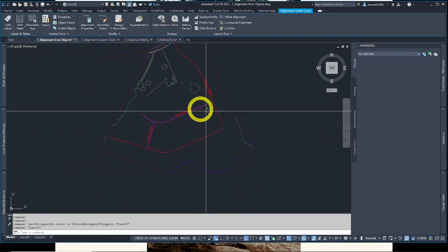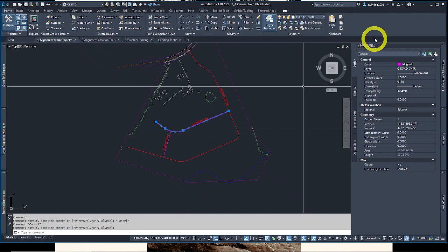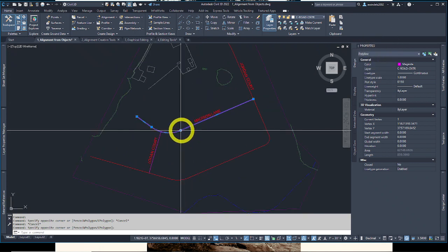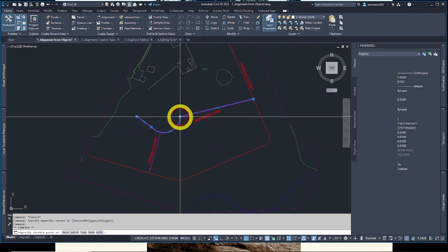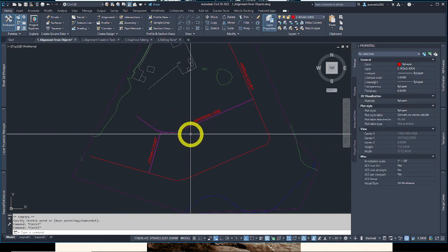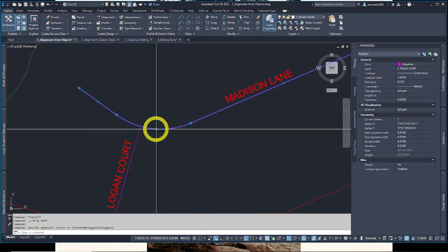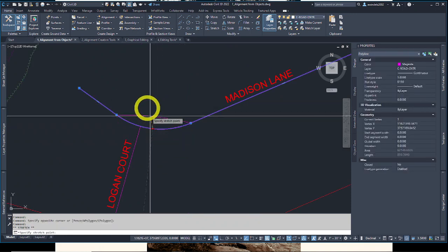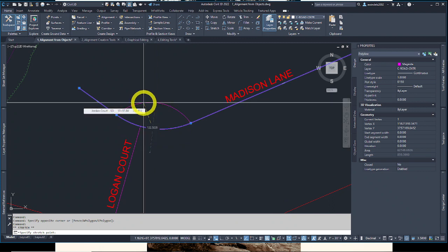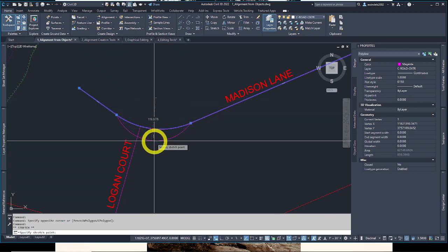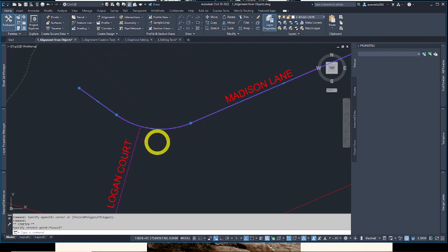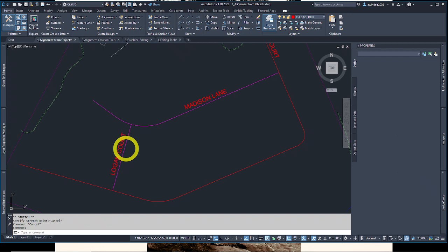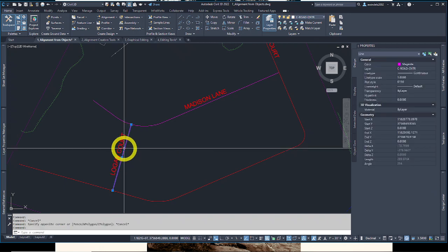And then if we go to these polylines, these magenta ones, they're regular Civil 3D polylines. They don't have that. They have more dumb grips, if you will. The blue regular AutoCAD grips of an AutoCAD entity that move kind of independent of one another. They don't have constraints, free, floating, and fixed to each other. They just move where you tell them to and draft them to in various ways. Same with this polyline. It's just saying, look at the difference.